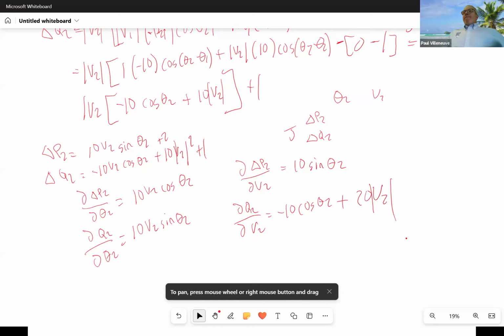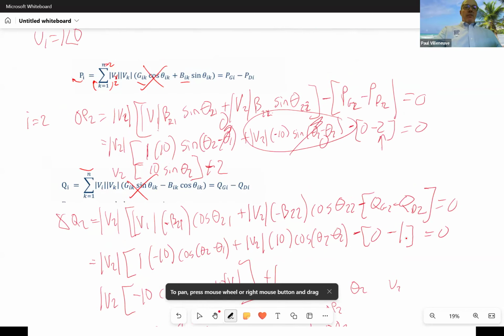Yes, sir. Before you can't find delta P2 and Q2, you don't put delta 1 or V1 or delta P1... I did have them. They're in here, aren't they? I see V1 right here and theta 1 right here. But V1 is 1 and theta 1 is 0, and it never changes. So I'm certainly able to keep them as variables, but why bother? I'm not adjusting them. So if you can spend a little time looking through it with some intelligence and saying, hey, this is 0 and this is 1, they just drop out. And then it makes your partials much, much easier to do.